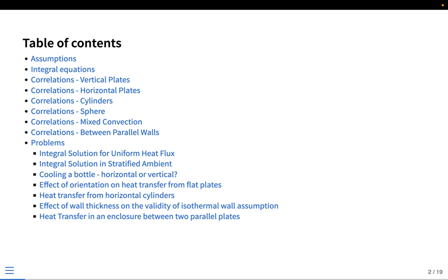So for now, only the correlations will be presented, and you have to select the appropriate correlation based on the appropriate criteria, and then use it to determine heat flux or temperature, whatever is being asked in the problems. We'll take up each problem in different cases and see how the Nusselt number correlations can be used to determine the heat transfer or temperature distribution.